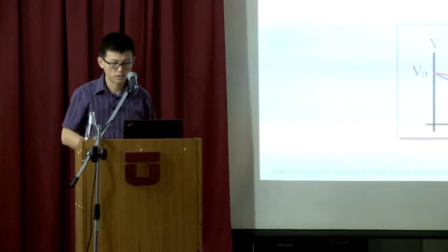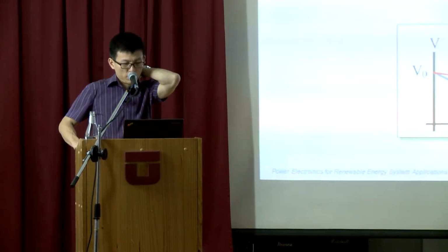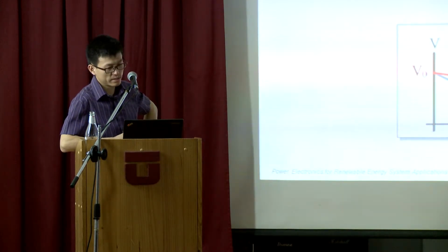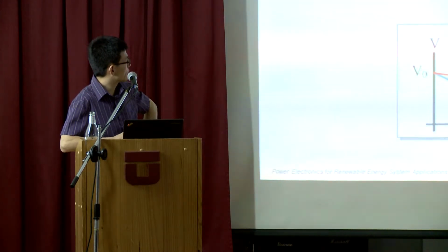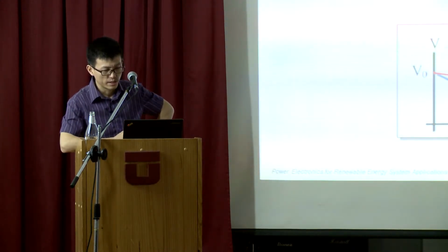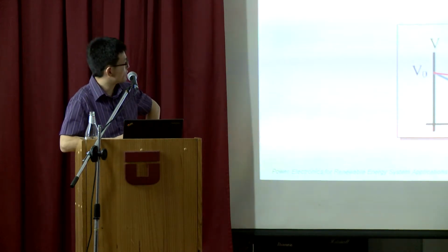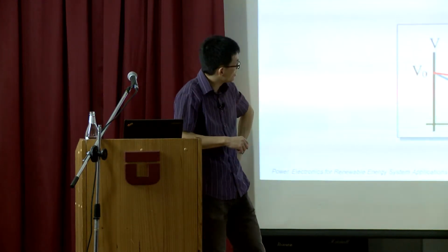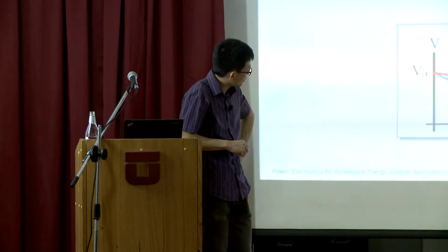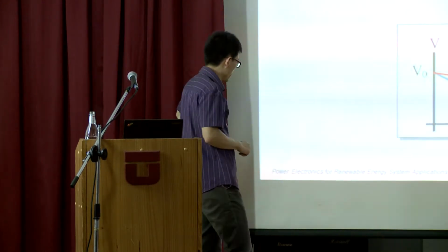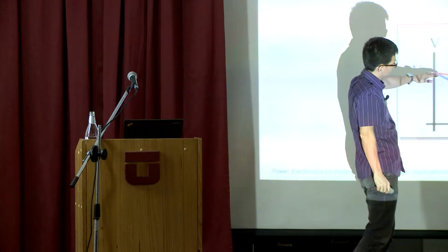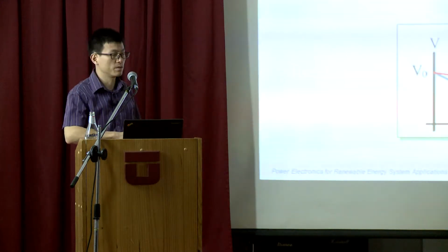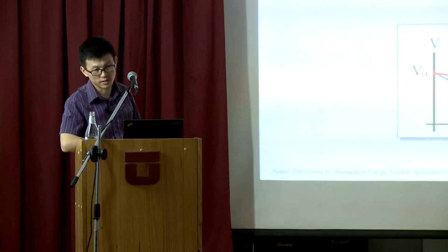Again, the same for the global droop gain for the current mode global voltage feedback. This global droop gain looks like this. What's really happening is you find out this global droop gain doesn't matter whether it is current mode or voltage mode. Compared with the individual droop gain, the stiffness is always increased. This is the individual one. This is the total or the global droop gain, which is always stiff. The stiffness is always increased.